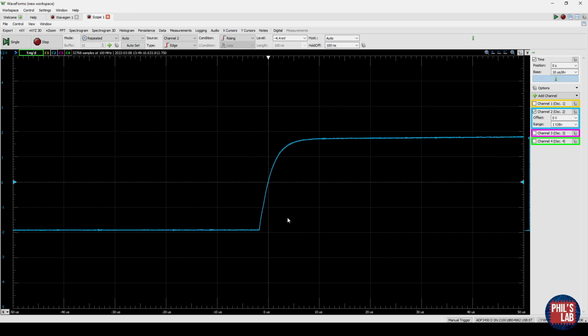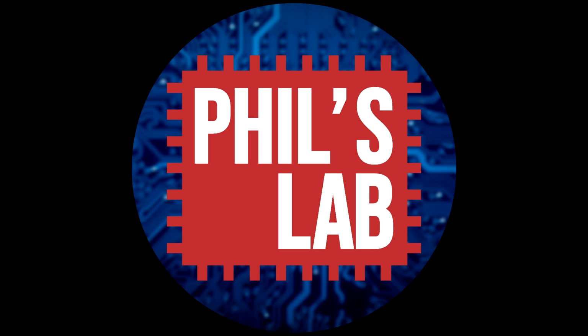If I increase it to 100 picofarads, you can see we have even slower slewing. Now, increasing the dominant pole capacitance does improve your stability margins, but of course you'll have much slower slew rate. So I can switch it back to 22 picofarads, and you can see this changes the slope of this rising edge, or how quickly this amplifier can slew. We also see, because we get stable input-output, that for the gains we're looking at, the closed-loop system seems to be stable.